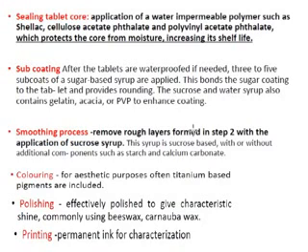Then, when we are spraying your sugar solution, there might be chances that the surface of the tablet may not be smooth. So to give the smooth surface, or the attractive look to your tablet, we have to go for the smoothing process. So the third stage is called the smoothing process. Here generally we give the smoothing by removing the rough layers of your sugar coats which are formed while giving the coat of sugar solution. Generally here we can use some cloth to give the smoothing process.